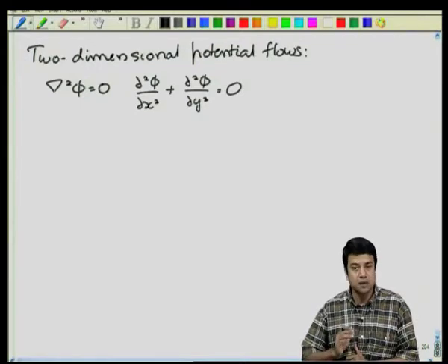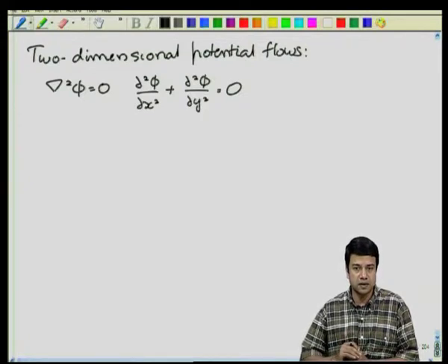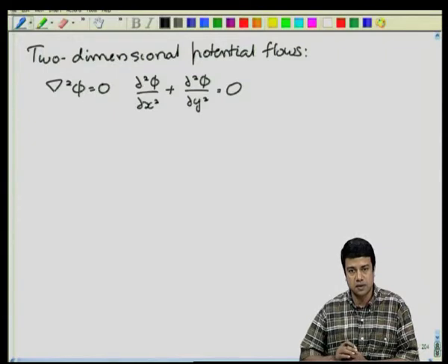The solutions that we get are in general applicable to any case where the field satisfies the Laplace equation. It applies equally well to the diffusion equation for temperature and concentration as well. But in this particular case, we will apply it to the case of potential flow equations.